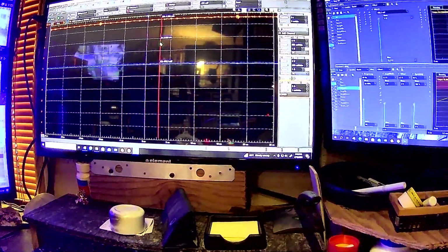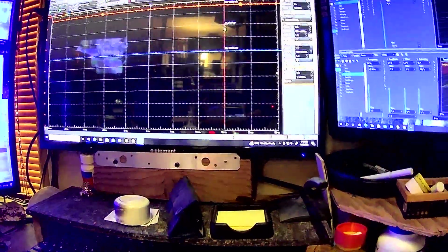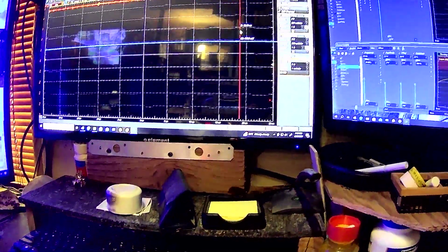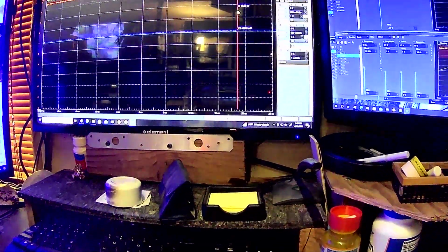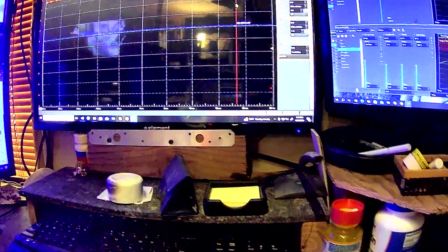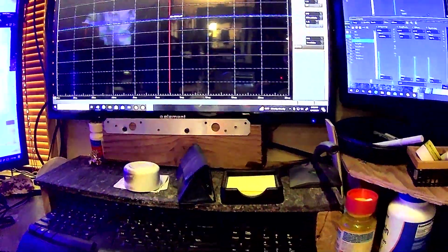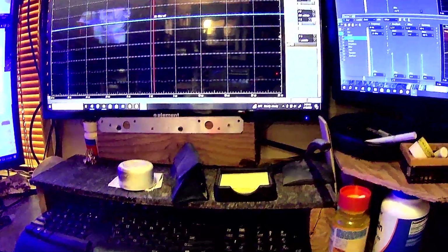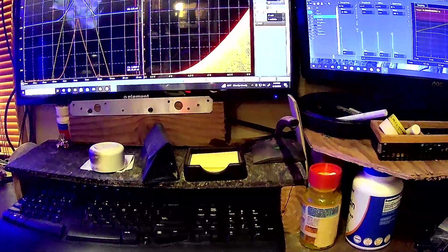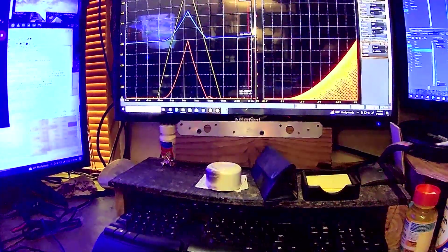It's looking at voltage in versus voltage out and doing a frequency sweep. That's not what I'm interested in. I'd be interested to see if I could do a measurement that takes the peak-to-peak voltage of the current waveform and the voltage input waveform, and see if it can generate a transconductance estimate based on the amplifier screen, since there's no good way to do that directly off these other measurements. Let me try that, and I'll get back to you in a sec.